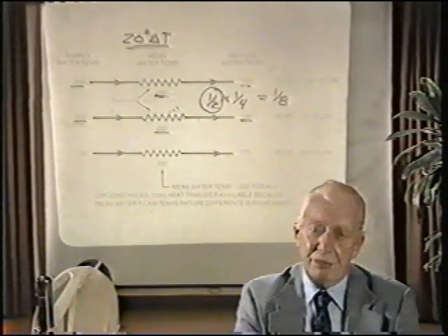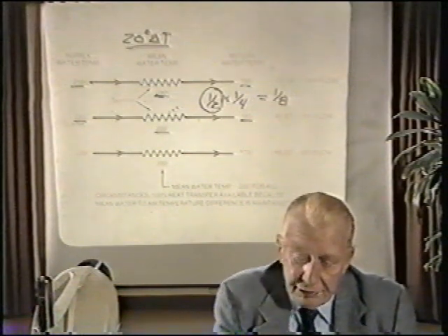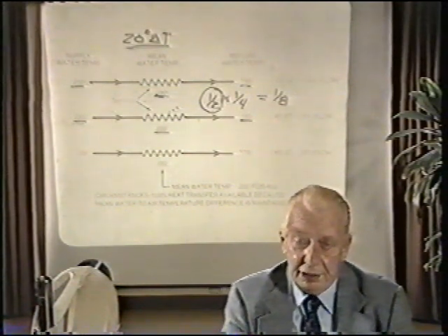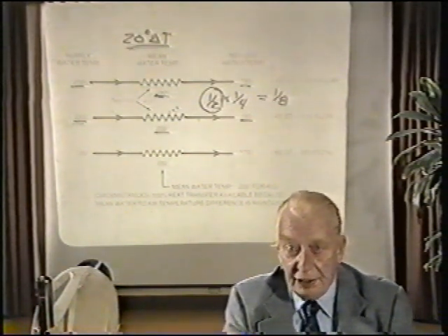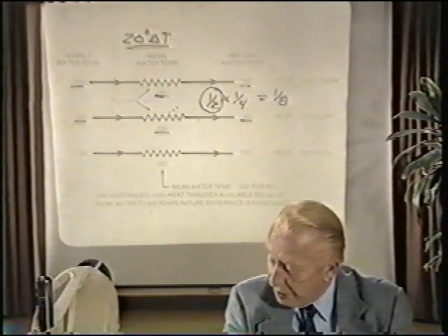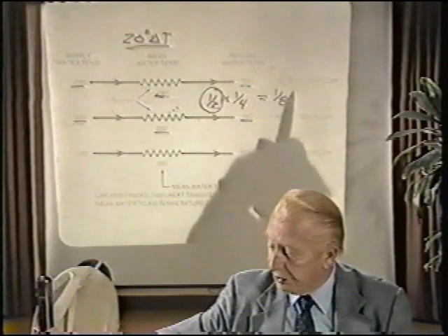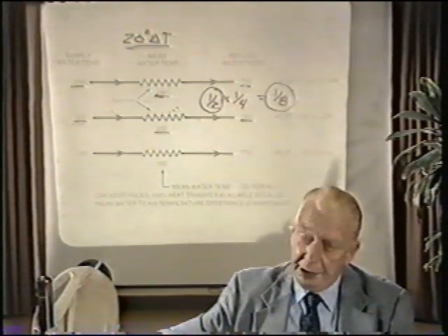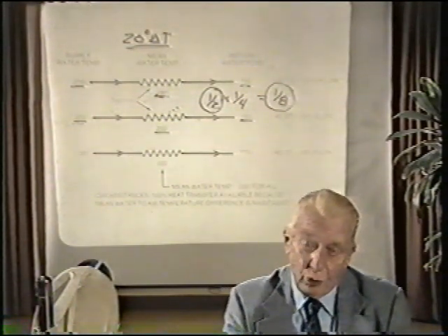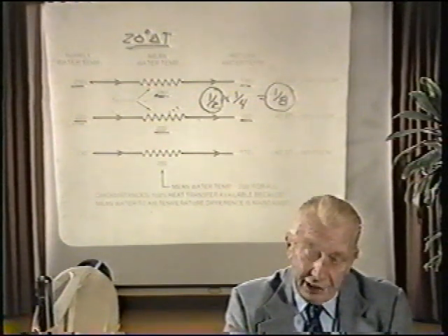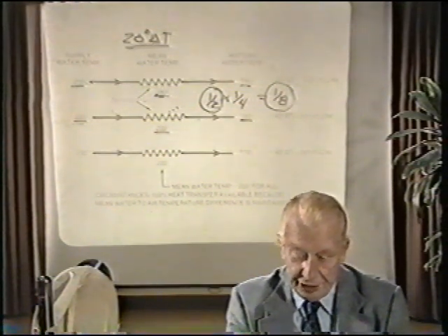So we can, for many of our systems, reduce flow rate to 1/2 of that originally intended, and because of this, finally reduce our power input to the order of 1/8, providing again that we have provided the necessary flow balance.